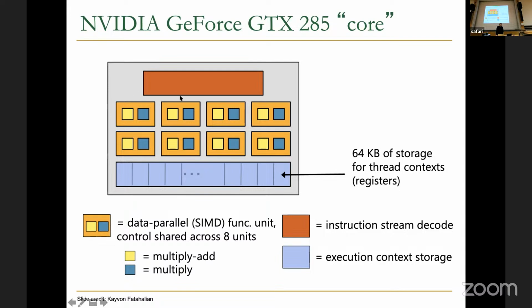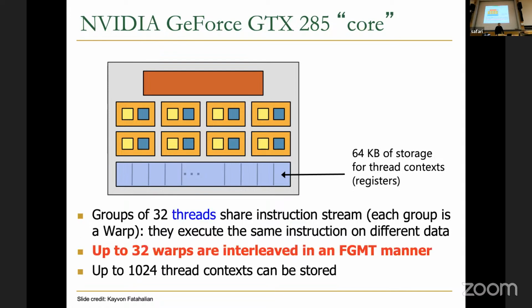Today GPUs are more complicated. For example, the latest GPU, the H100, I guess has a 256 kilobyte register file per core, which is huge. That's also not the only thing. There are some papers showing that we need a much larger register file. So in reality, you need to increase the register file even more.